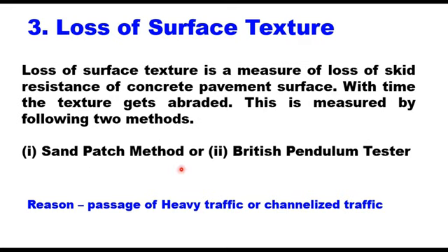The sand patch method is simple. It can be used in field. It is a volumetric approach to determine the average micro texture depth of the paved surface. Procedure is simple but very time consuming, and it cannot be done for the whole section. It can be done only on locations. British pendulum can also be used either in the field or in the laboratory.